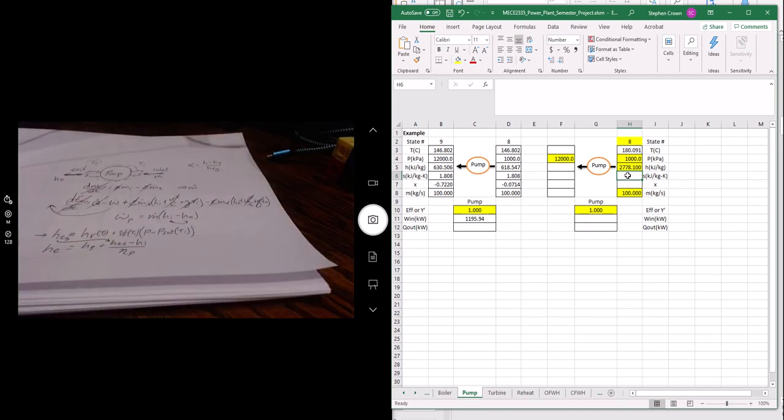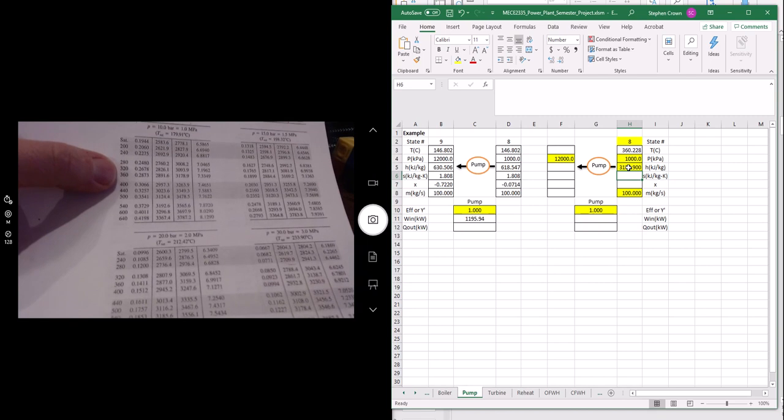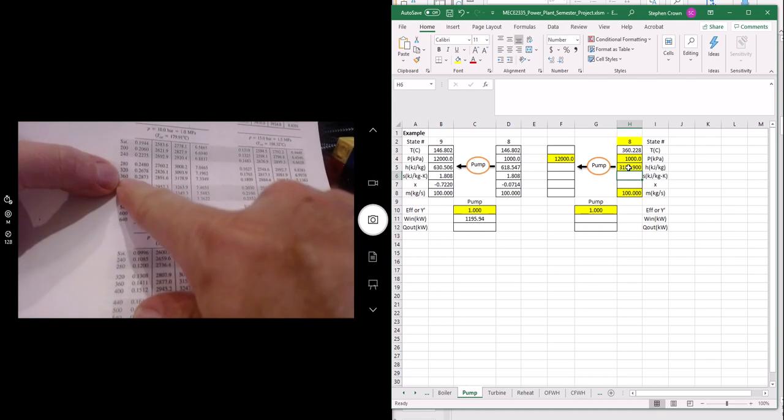And if we go to the superheat values, and so 1 MPa, let's type 3178.9. And we get 360.228, so maybe 1 or 2/10 of a degree difference in the temperature. So we can use this function reliably. We won't always get exactly the same values as the tables.